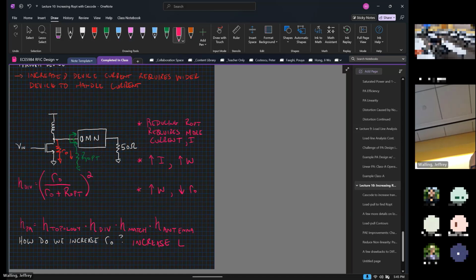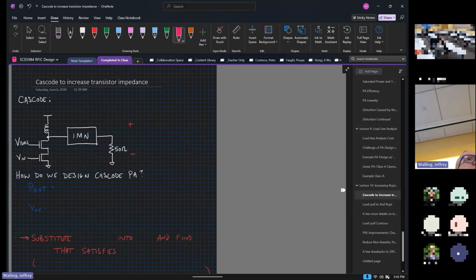Cascode. Okay. Now, you'll recall I've told you before, I believe in this class, that sometimes nowadays they call a cascoded transistor a stacked transistor. I believe that the people that do this, their interpretation is wrong. Cascode dates back to the vacuum tube era, and they didn't put a limit on the number of tubes that they stacked in principle. Now, in practice, tubes were expensive, so they didn't necessarily stack 10 transistors, but there was nothing really in the original work on cascodes that said that they couldn't. So I think a cascode and a stack are the same. I'll argue that until they draw and quarter me and send me out to the drill field.